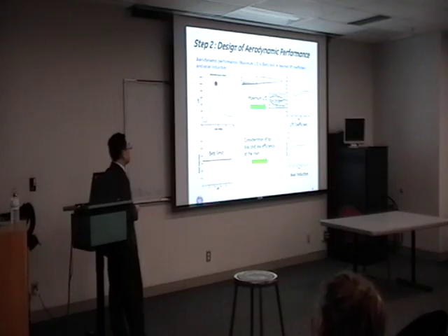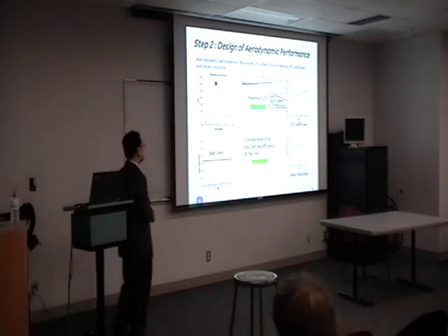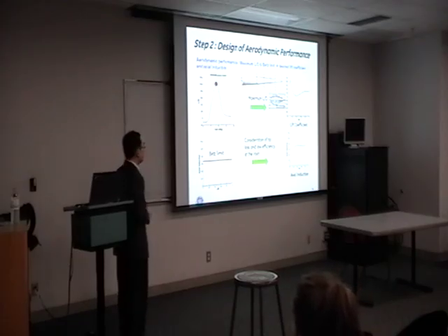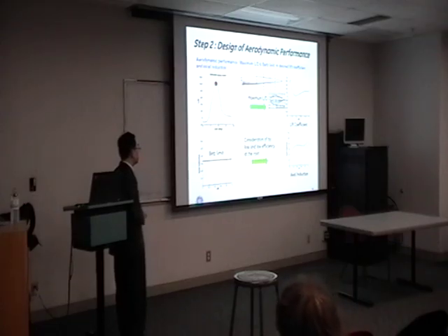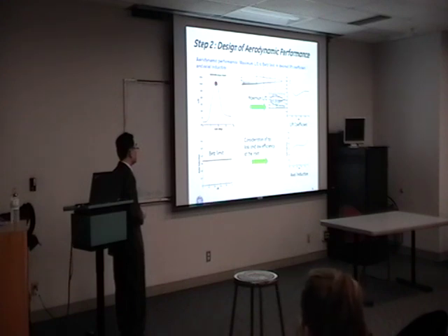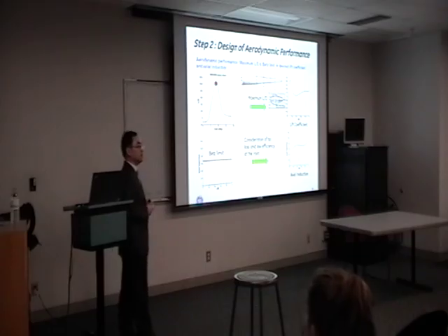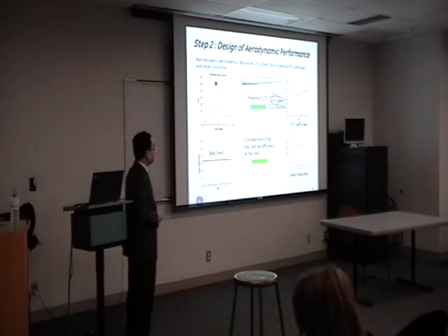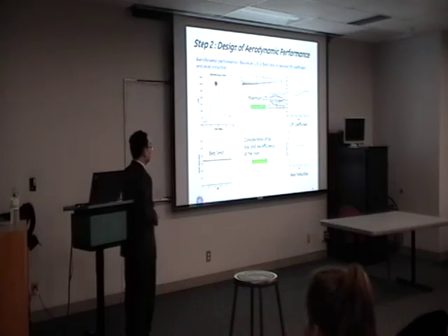Theoretically, the maximum CP comes from a constant value of axial induction, which is 1/3, and this is called the Betz limit. But practically, it is impossible to maintain a constant axial induction because we need to consider the tip loss effect and root loss effect. Also, from a structural point of view, constant axial induction is not the best solution. However, we like to maintain the 1/3 axial induction for most of the blade, and we need to give some variation at the tip and at the root.